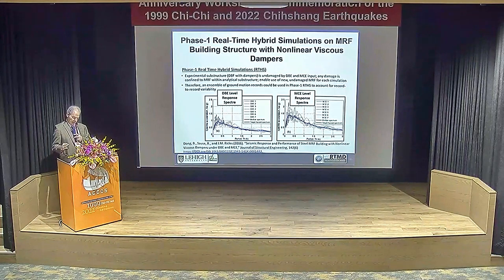Now, in this system, what primarily yielded, if any, was damage in the RBS beam-to-column connections. But it was mild, as you see. So we can repeat this many times because we can model that analytical substructure of all that damage numerically. Experimental substructure remained linear.